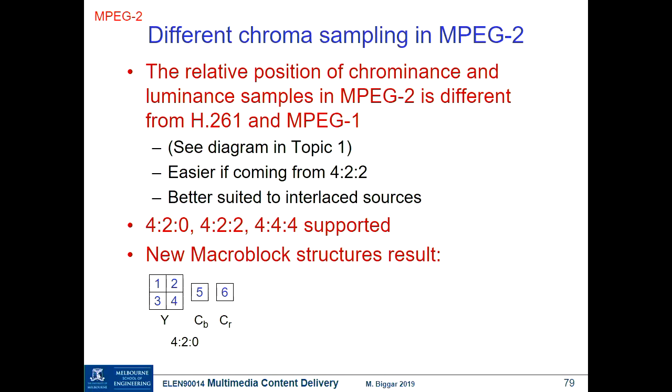I don't want to take the time to talk about this alternative chrominance and luminance sample position. Having it on the slide, I just need to say what I'm talking about. If you remember, back when we were talking about 4:2:0 subsampling, reducing the resolution for the chrominance signals, we created a pattern of chrominance samples where the chrominance was an average of the surrounding 4 pixels, and therefore it was logically located right in the centre, in between them.